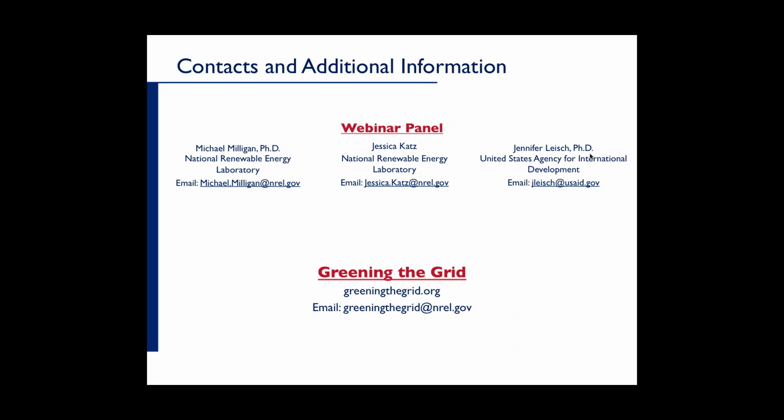Actually, I may not even know what demand is because now if I have a lot of solar PV on the distribution network, I can't really tell if a cloud has come by and reduced solar output or if somebody just turned on a big massive load of some kind. And so I think one of the biggest challenges is to figure out a way for the distributed solar to be visible to the power system operator so that decisions on how to best operate the rest of the system can be made efficiently.